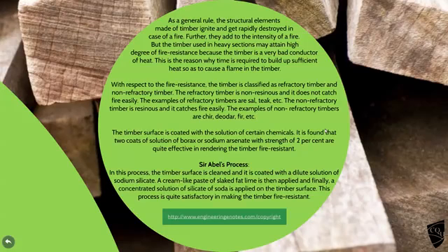The timber surface itself, you can coat it with a solution of chemicals. It's been found that two coats of a solution of borax or sodium arsenate, don't lick your fingers, with a strength of about 2%, really does improve timber's fire resistance by a reasonable amount.